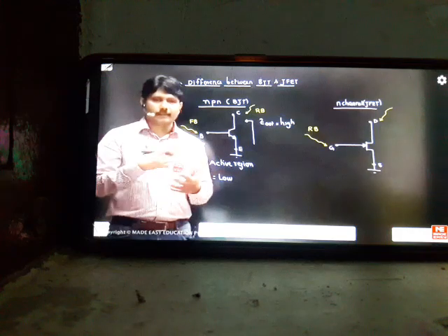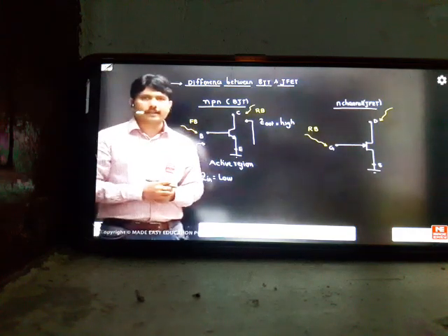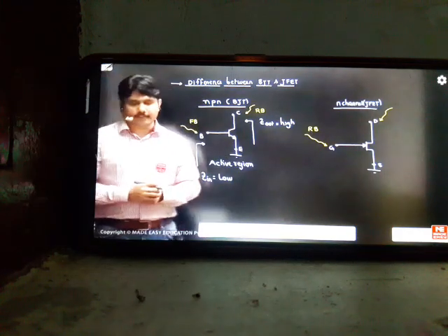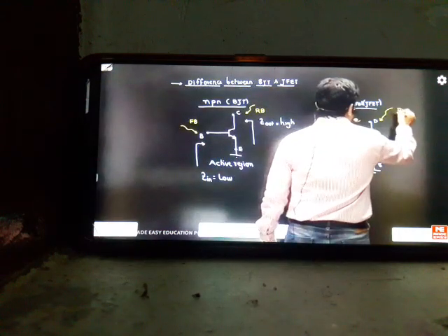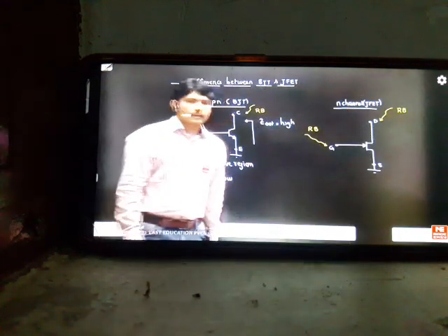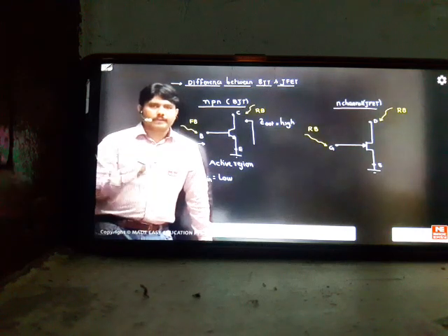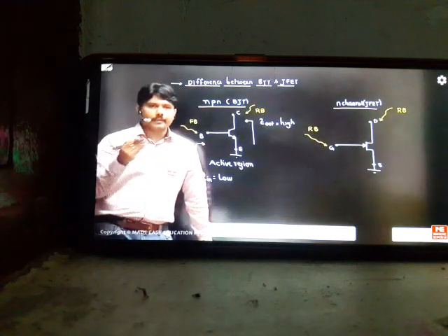Why we make it reverse biased will come in the next explanation, called block diagram analysis. Here I'll explain the content. Here reverse bias is important, always. Have this knowledge: the input should be reverse biased. And the drain should be the same, it should always be reverse biased. So can you see the surprising point in the class? Your N-channel JFET, if you want it to work in the active region, has to work with input reverse biased and output also reverse biased, then only it can work in the active region.